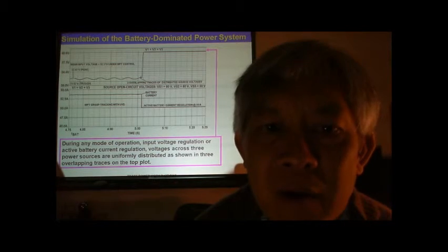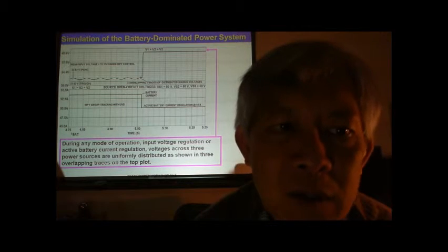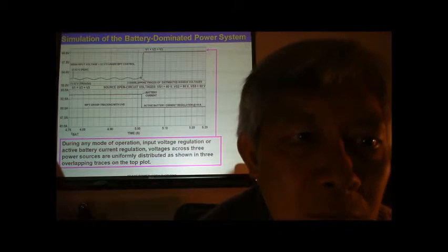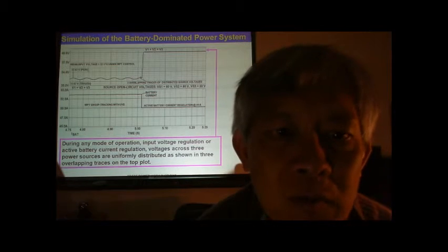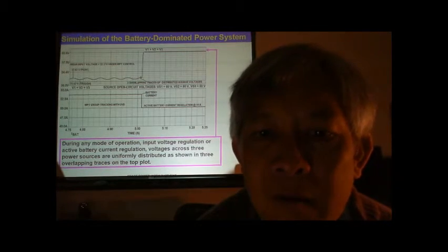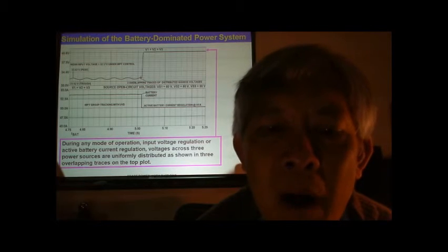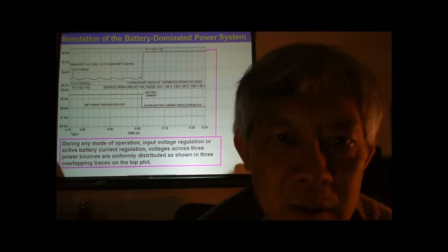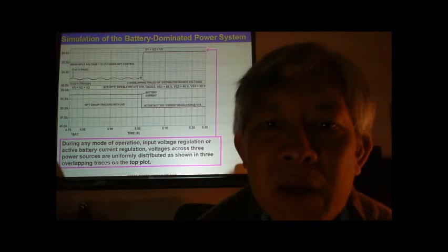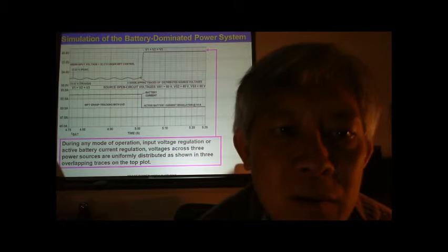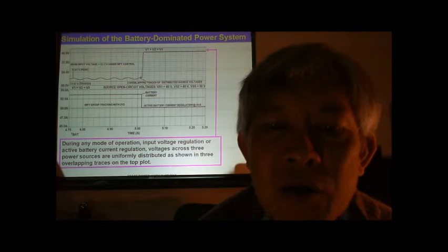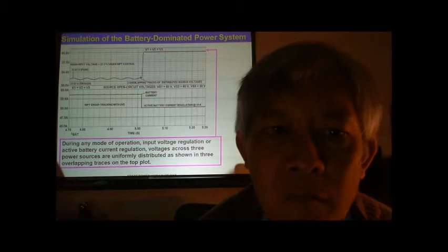During the maximum power tracking mode, the sourcing voltage has the optimum power voltage around 32 volts with a low frequency AC ripple of about 20 Hz superimposed on the sourcing voltage, signifying that the system is in maximum power tracking mode. In this mode, the battery current is charged at the maximum rate the power system can offer.